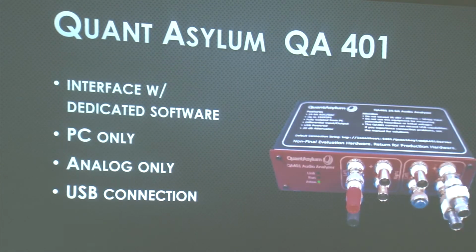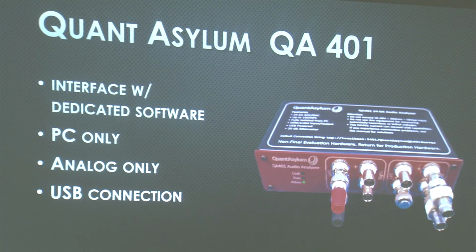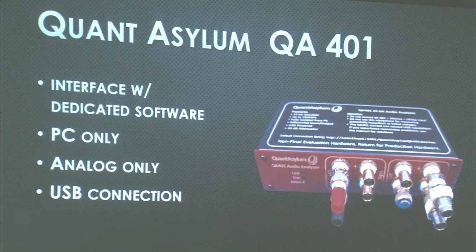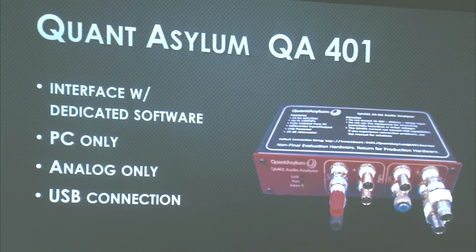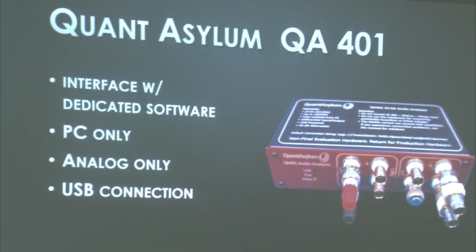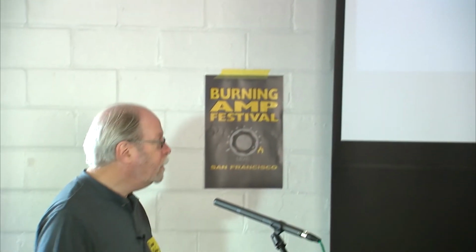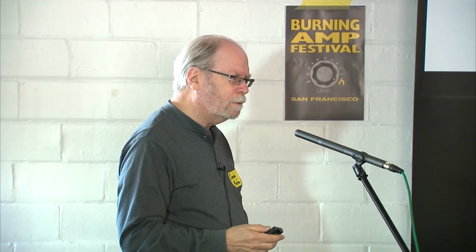Okay. Then, this product's been around for a little over a year. It's a nice little self-contained, dedicated audio analyzer. What it will do, it has differential inputs, balanced outputs. It's good for up to 30 volts. It has an automatic attenuator, so if you feed it too much for the range it's at, it switches that in. It's useful, it works, the software is pretty good. I mean, it's a decent one-stop solution. It has its limitations, and you do have to learn how to use it like any of these. If you needed to get one box to go turn it on as a hobbyist and go make measurements, this is a really valid starting point. I think they're around $500 right now.